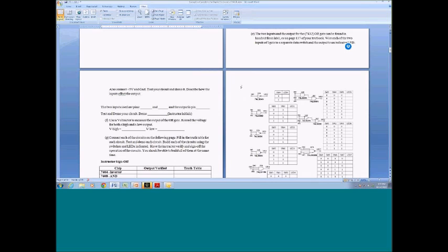It's mind-numbing how much detail is in how to do this. Talking about keeping your leads short, keeping color coordination, because inevitably with students it's a rat's nest of wires. They can't see what's going on, and Ray will go to the point of even ripping all the wires out of a student's board and telling him to redo it. I'm not quite that aggressive in the way I do things, but the document that he put together is spectacular. I'm going to ask Ray if he'd be okay if we shared it, because it's really well done and in such amazing detail that I think anybody who's really trying to wire up circuits should have it.